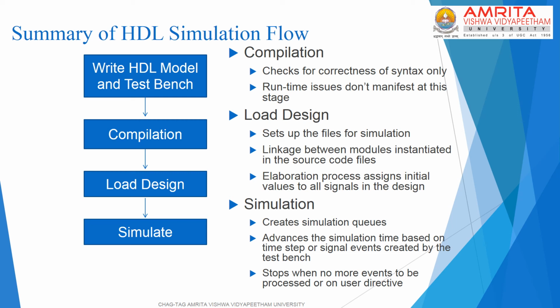The simulation process continues until there are no more events in any of the signals in the device under test, or until the duration that is specified by the designer. So there is an option for specifying the duration of simulation. In either of these cases, the simulator stops.